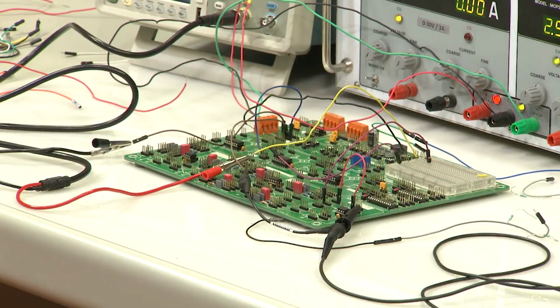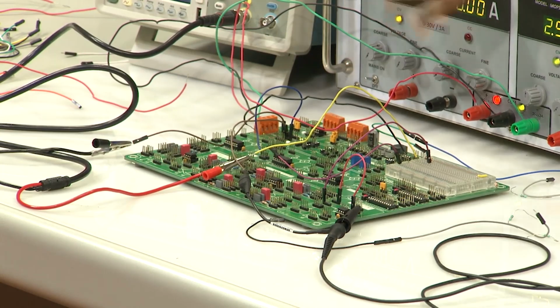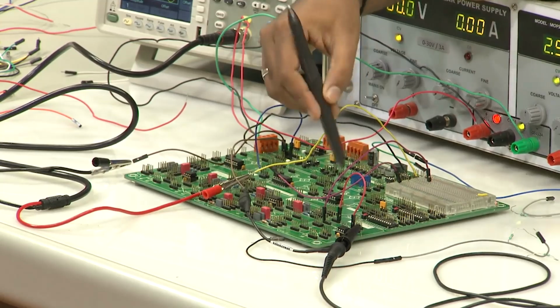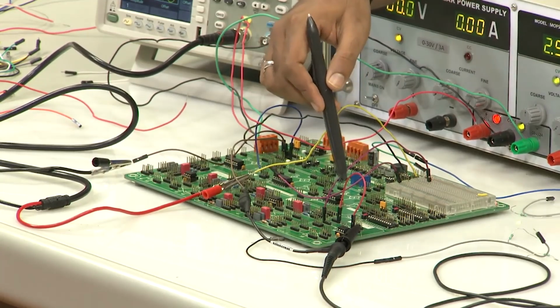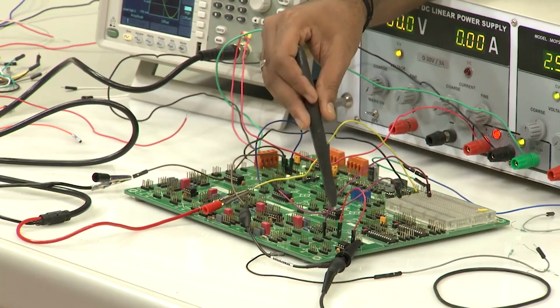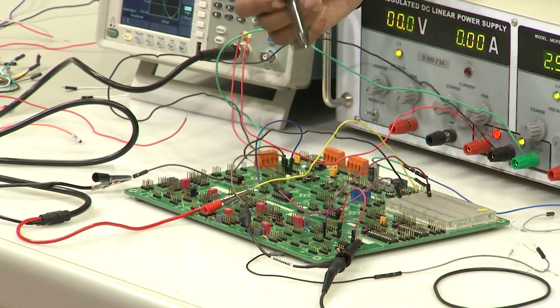We have just now seen the op amp connected as an inverting amplifier with a gain of 2.2. We have seen how the output is varying with the input, and what the input range is, correct. Now, the best circuit to demonstrate the effect of gain and the range of an amplifier is the voltage follower circuit. We have connected the voltage follower circuit on the board. So, what is a voltage follower circuit? It is an op amp circuit that has unity gain, so it is also called the unity gain amplifier.